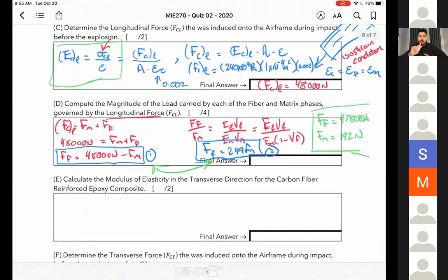So my method only works for stage 1 because I substitute stress for modulus times strain. Yes, so your method would actually work in both cases as well, but you would have to use the stress value, you couldn't substitute E over epsilon.